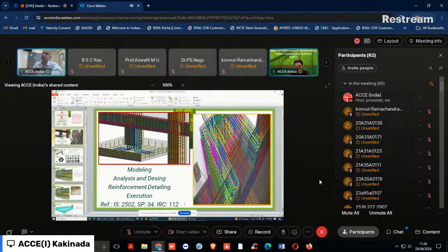This L bend is compulsory for small size footings like 1 meter by 1 meter or 1.2 by 1.2 meters. For small size footings, having a lower projection length, you have a development length requirement of 51 d, which necessitates the L bend. Putting an L bend for all the footings is sometimes a wastage of money. That is an unwanted practice that generally takes place in the field.